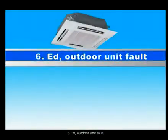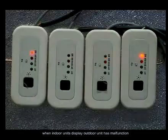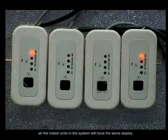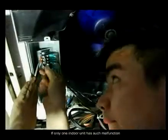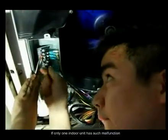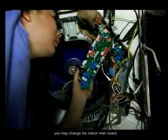6. ED outdoor unit fault. Repair instructions when ED appears. When indoor units display outdoor unit has malfunction, all the indoor units in the system will have the same display. If one indoor unit has such malfunction, after confirming the wiring is reliable, you may change the indoor main board.